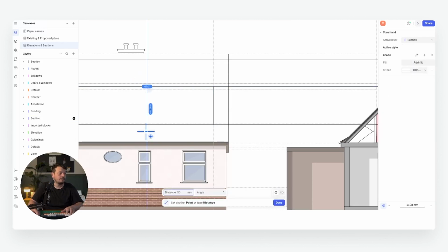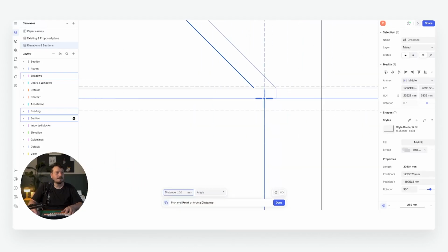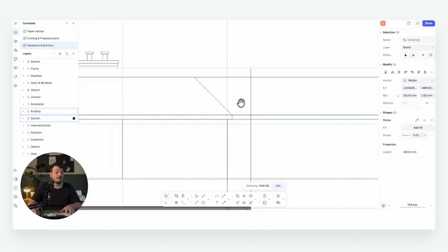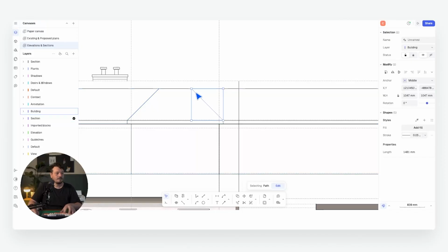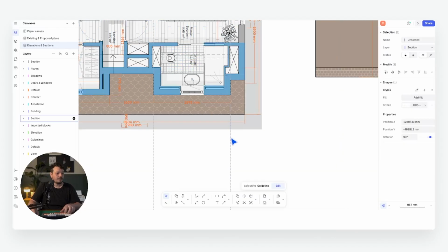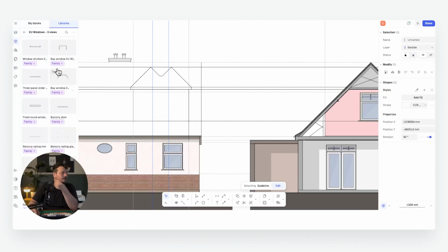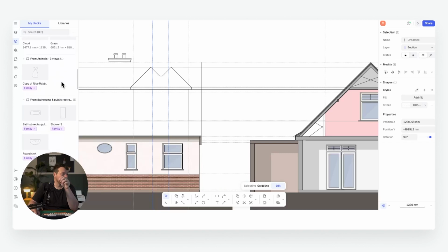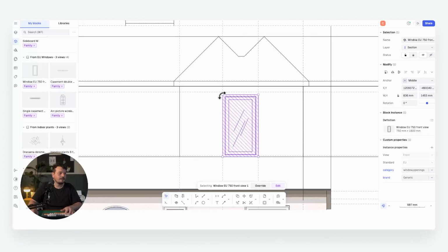Bring in those two side walls, and obviously again we've got our sort of roof pitch, our roof overhang that's sitting sort of here. And what I really want to do is bring in this sort of arts and crafts style. So I'm going to have a sort of double pitch roof that has this little valley feature. And then we can see where the window sits centrally within that space. And again, I can go to the Rayon block library and I can find either a window that I've used before. So if you have a look into my blocks, for example, you can find some of the windows that we used previously. So we probably want the window head to align there.